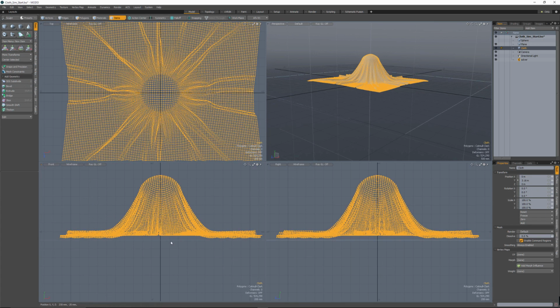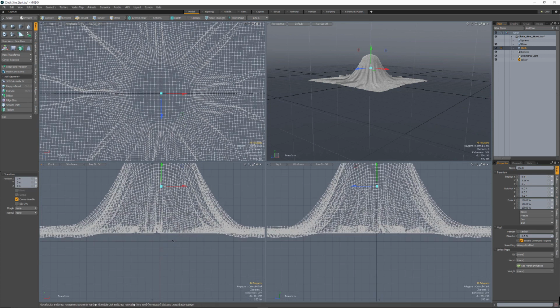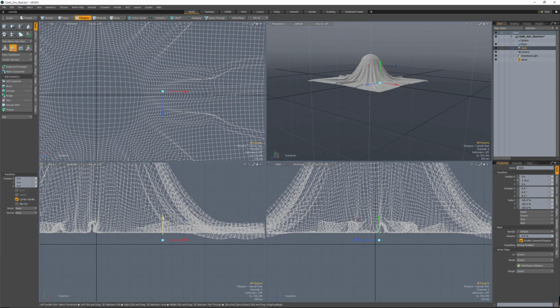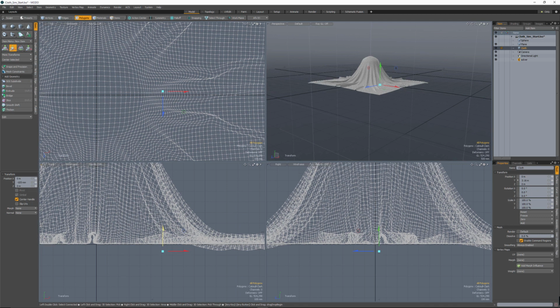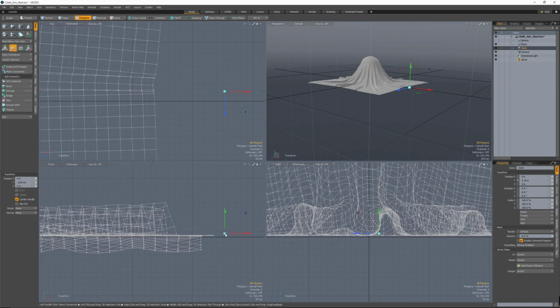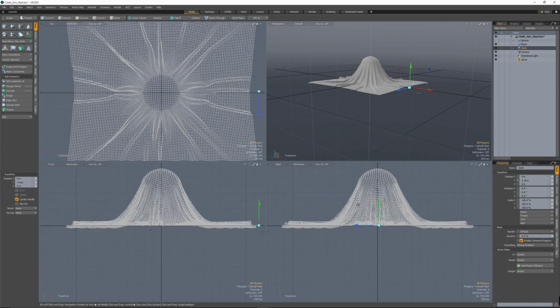So I'm just going to clean this up so that it's sitting squarely on the ground. Let's start by going over to Polygon Mode, and I'm just going to grab this whole guy here. Let's zoom in on this front view, and I'm going to pull it down so the bulk of the object, where we can see we've got flat edges, is sitting right about on the ground plane. We can see we've got this edge here extending off. Maybe we'll go down just a tiny bit more. So something like that. Okay.